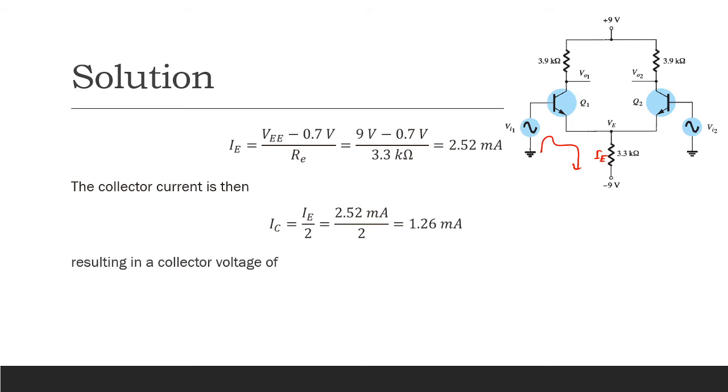Since we already have IC, we can now solve for Vout1. Remember, it is labeled VO1 and VO2. Now, that is just similar to the collector voltage because it is the voltage at this point, at the collector of your circuit. You might be confused: sir, why is it not VC written there? That's okay. We can loop again here, or just use the equation we derived earlier, and we will arrive at an answer of 4.09 volts. That's it. That's how we solve it.